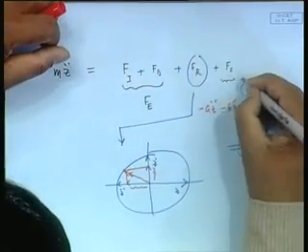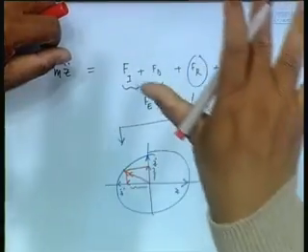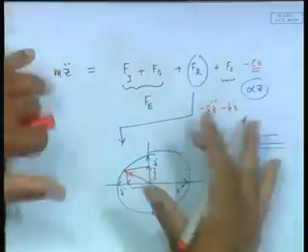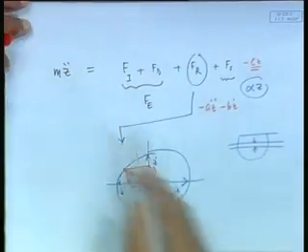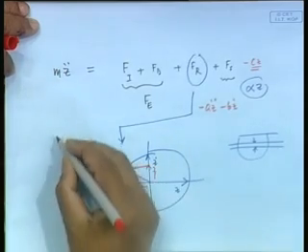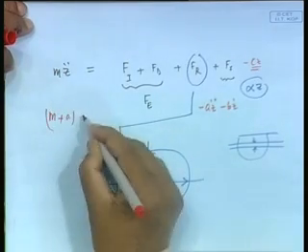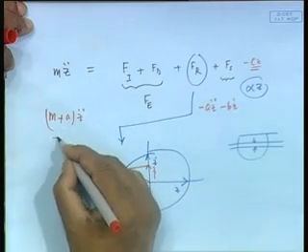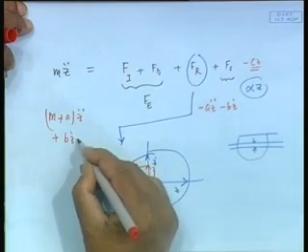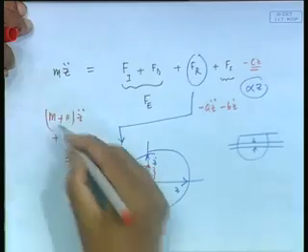This I can write as minus z. Actually, the minus sign always comes because if I do plus z, the force is in the other direction. So it looks like that. Now I reassemble that equation. Very interesting, I can bring it to this side. So I end up getting an equation like (m plus a) z double dot plus b z dot plus c z is equal to F_e.